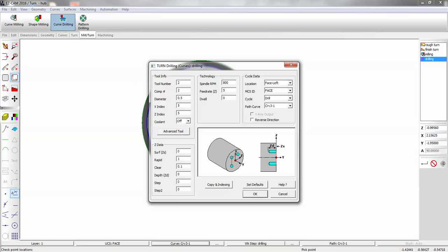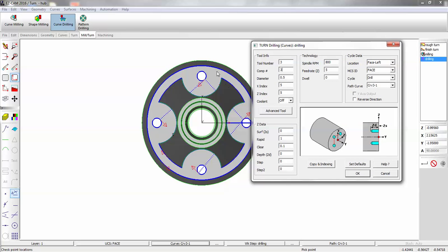Tool 3, offset 3, 1/2 inch diameter. If I wanted to, I could use our dimensions in check the radius. Depth, if you remember, it was -2.4, so we'll go 3 inches deep. The cycle type is drill, that's just going to feed through to the end. You could simply choose a deep hole or chip break if you want to peck.